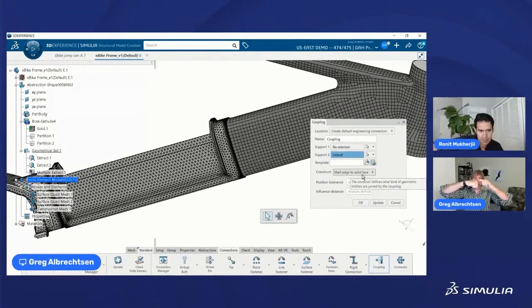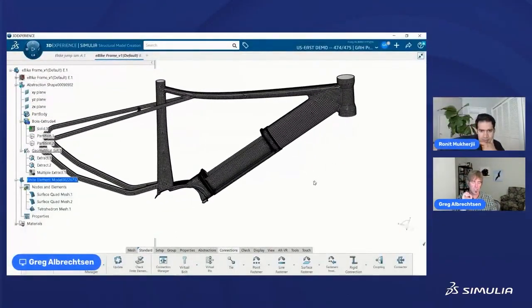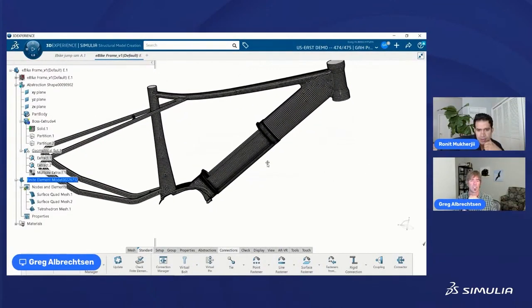Obviously, if you're really worried about the stresses and strains in this little joint, that's not the proper way to model it. But it's a perfectly wonderful way to get the overall stiffness of your whole model, if your stresses of interest are out here. So a lot of the time, I would do this mixed meshing just to make things solve faster. And if I'm really concerned about that junction, I will come back and do something different specifically for that.